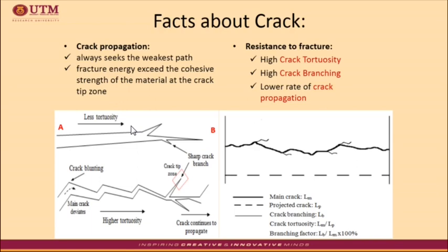This is the case because the material is able to provide a choice of crack paths to prevent sudden catastrophic crack growth, which is known to result in spontaneous fatigue failure because a propagating crack always seeks the path of least resistance. In other words, the catastrophic crack growth is inhibited by crack blunting, whereby the plastic deformation prior to crack propagation is increased.